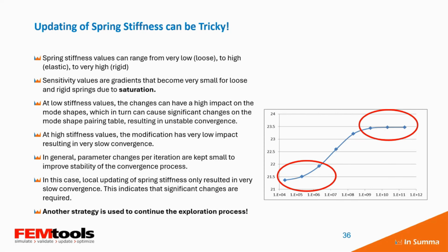There is, however, something to be considered about spring stiffnesses and updating, which can be tricky, which is something we call saturation. You see that this is a relationship between frequencies and stiffness, not necessarily for this structure, but more general, where we see that at high stiffness values, the sensitivity becomes very, very small.